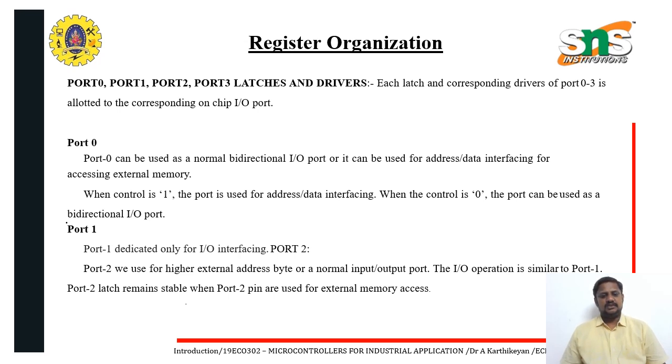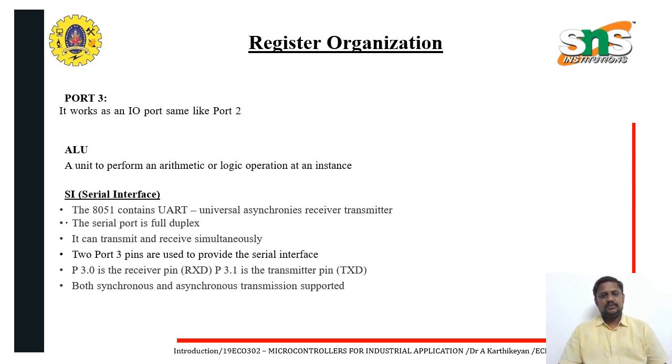As for port 1 operation, it is mainly an IO port, a normal input output port, and port 2 operates similarly to port 1. But the port 2 latches and port 2 pins are used for external memory access. And port 3 is used as an IO port, the same as port 2.